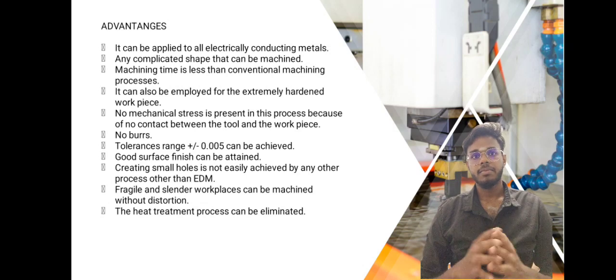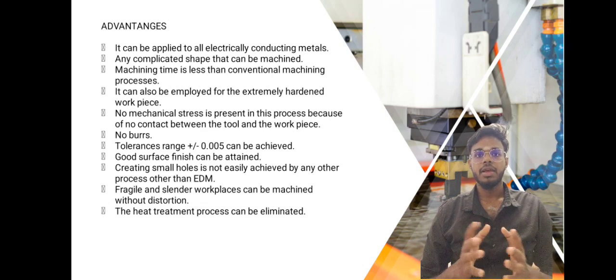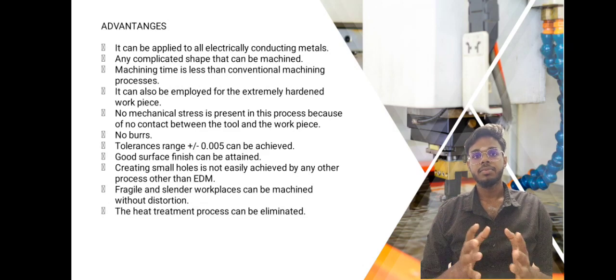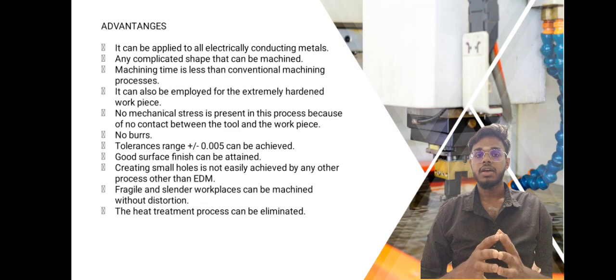The advantages of EDM: it can be applied to all electrically conductive metals and any complicated shape that can be machined. Machine time is less than conventional machining processes. It can also be employed for extremely hard workpieces. No mechanical stress is present in this process because there is no contact between the tool and the workpiece. No burrs. A tolerance range of plus or minus 0.005 can be achieved.